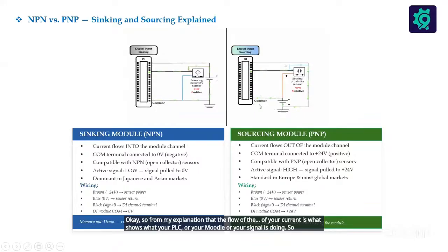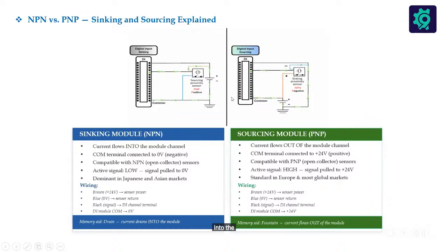They call this digital input sourcing because the positive signal is entering directly into the PLC here. This module is sourcing from outside in this case.